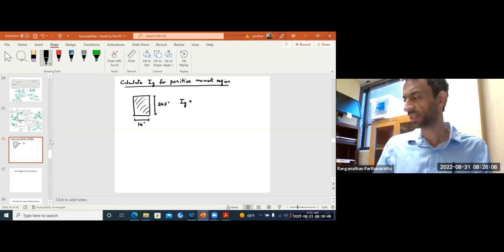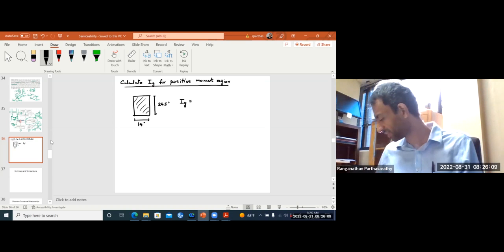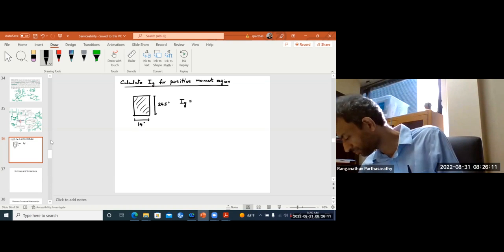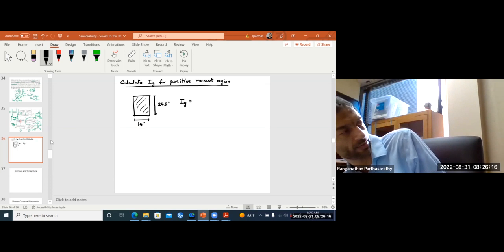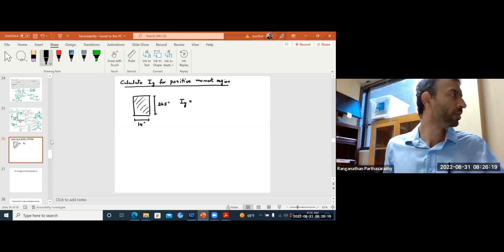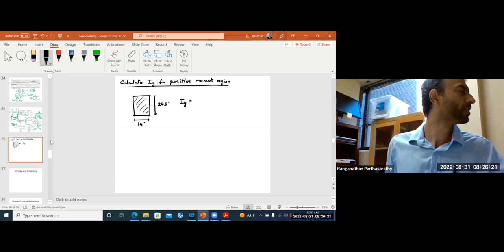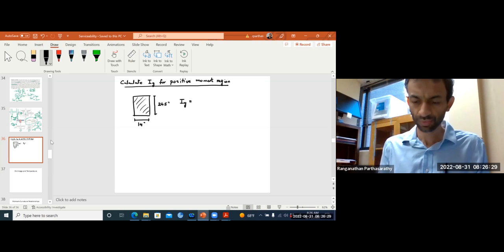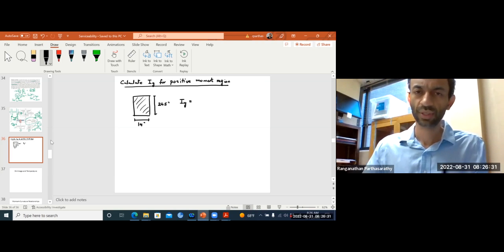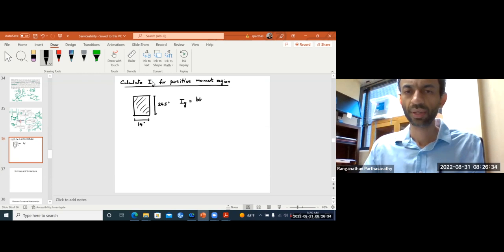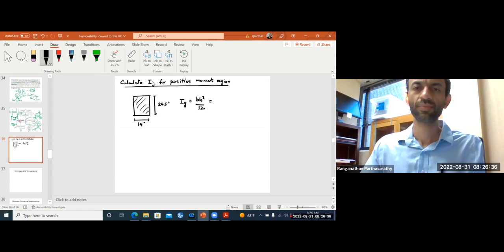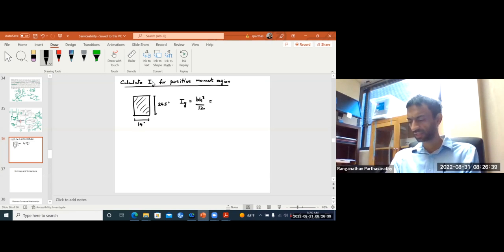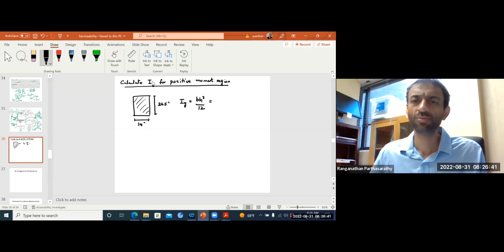So what is Ig? Can somebody quickly calculate and tell me? It is BH cubed by 12, right? This is the first step for deflections, that you get your effective moments of inertia.